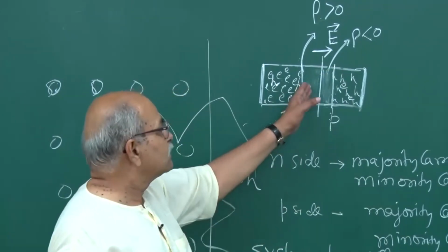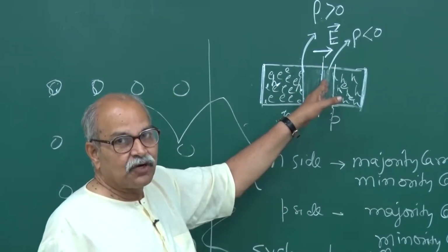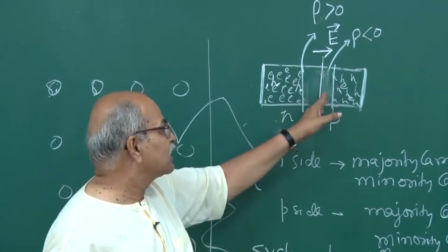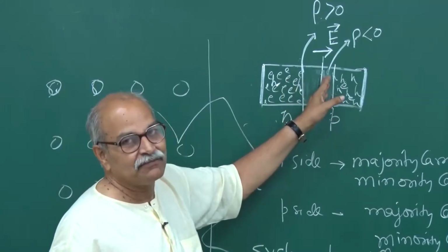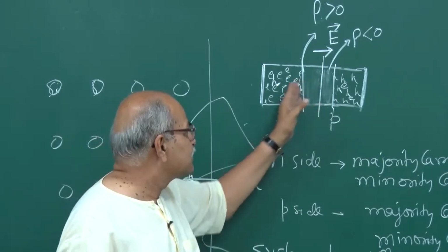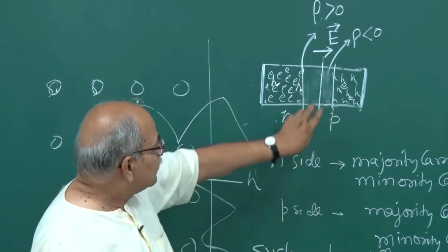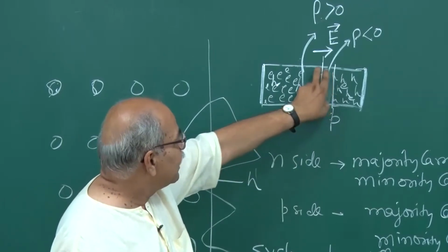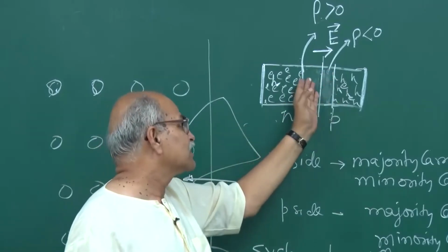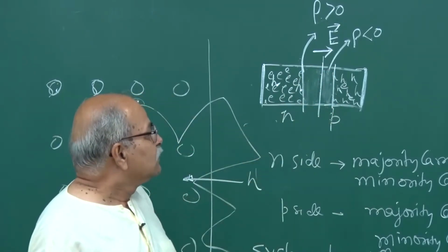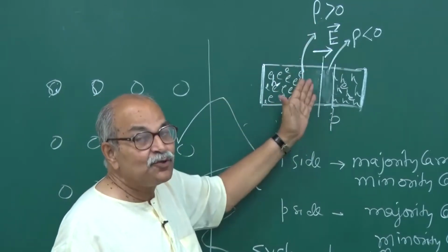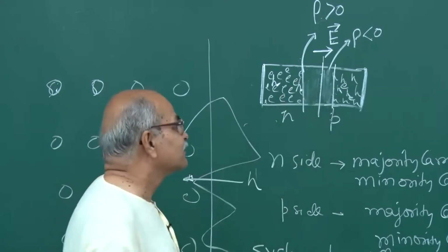So, in that same fashion, you will have no charge carriers left. The electrons which are diffusing to the right, because of the large hole density there, are trapped, and then if there are holes left, more electrons will come, and this width will be adjustable. As many holes are here, that many electrons will go from this side and fill, and both ways. So, what you find is, yes, there are charge densities, but you do not have charge carrier density.